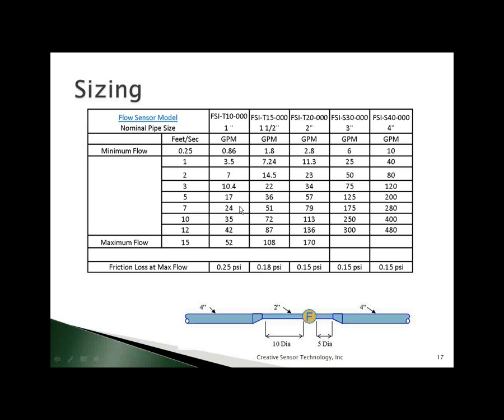much lower flows. And this becomes particularly critical when we've now found that most people are retrofitting systems, putting in drip irrigation in shrub beds and things, and generally reducing the size of some of the zones down to the 1 gallon per minute or down in that kind of range. Most other flow sensors in the industry today can't get close to these kinds of low flow ranges. So if you're looking at some of the other competitors, don't look at the high flow limit to their range, look at the low flow limit when you're comparing things.